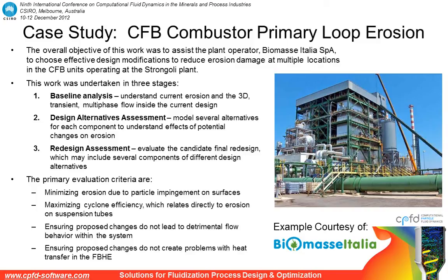So the 40 megawatt unit had to be shut down after only 1 month of operation for repair of the refractory. They subsequently made some changes to the cyclone geometry and were able to stretch that operating period out to 3 months. But a more typical service interval for a plant of this sort would be 2 or 3 years, not 2 or 3 months.